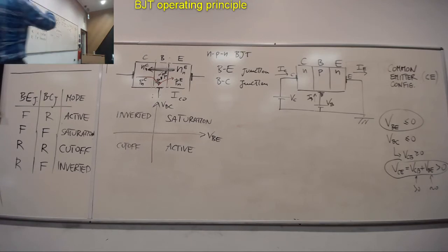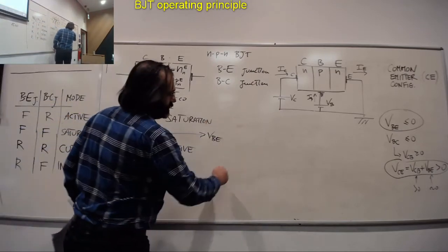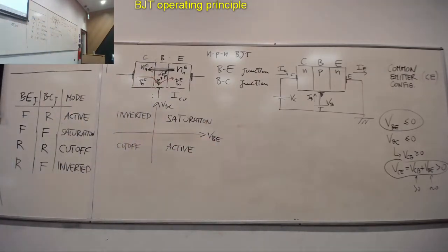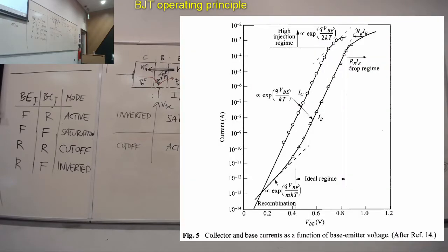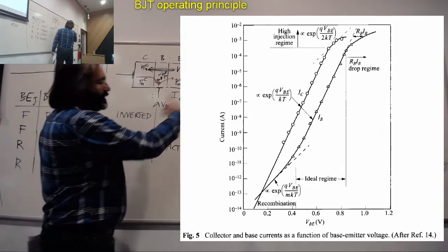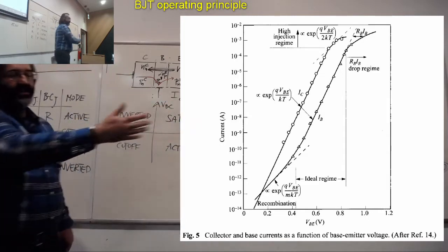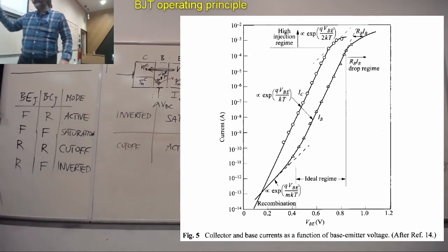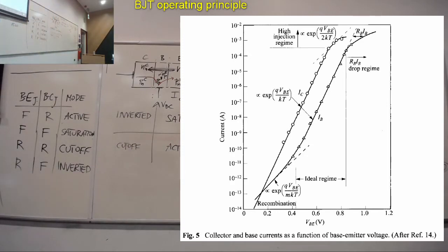We've seen the characteristic IC versus VCE on the screen, which I will show you now from a real transistor. But there is also another characteristic, which is this one here. We've discussed the output characteristic, if you like, the IC, which is the large current coming out, versus VCE, and the parameter there was IB. So this is called the output characteristic of the transistor.